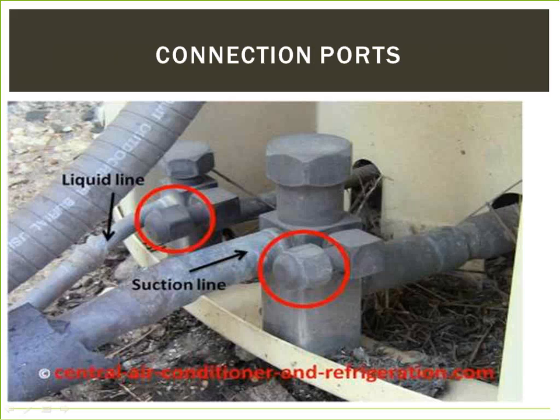Next, locate the AC unit's low and high pressure test ports. These will resemble tire valves attached to a tube, with the low pressure port generally on the right side of the AC unit. Verify with the unit's service manual if there is any doubt. Unscrew the valve caps from the test ports. Unscrew the blue low pressure hose from the front of the test gauge's manifold and screw it onto the AC unit's low pressure test port. Unscrew the red high pressure hose from the front of the test gauge's manifold and screw it onto the AC unit's high pressure test port.